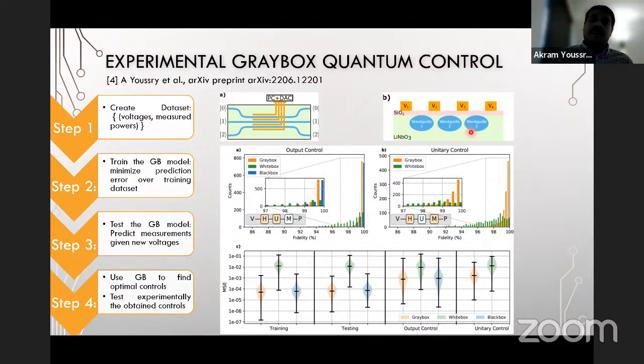So what I think probably is happening is the following. If you see the architecture of the device here, there is a fan in and fan out. It's not straight waveguides from beginning to the end. We have to do this fan in because these are ports that have to be connected to optical fibers, so they have to be separated with some minimum distance, so you can actually couple the chip to the optical fibers.